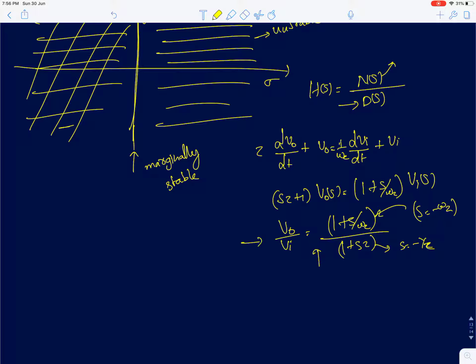So if you can see, the transfer function can be represented as a numerator polynomial and a denominator polynomial. When you equate the denominator to 0, the roots of that equation, the denominator polynomial, are called poles. Now by just knowing those roots, you can actually predict a lot about the system. You can say whether the system is unstable or stable.